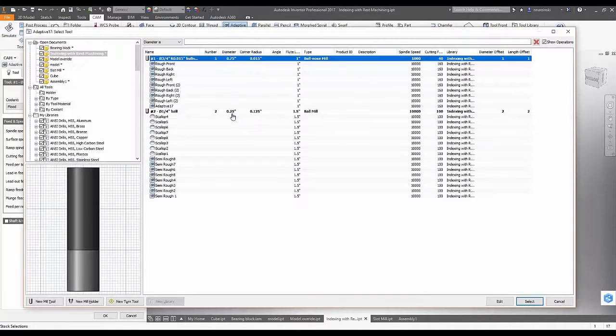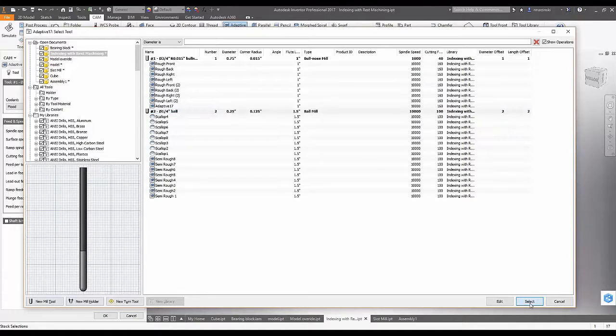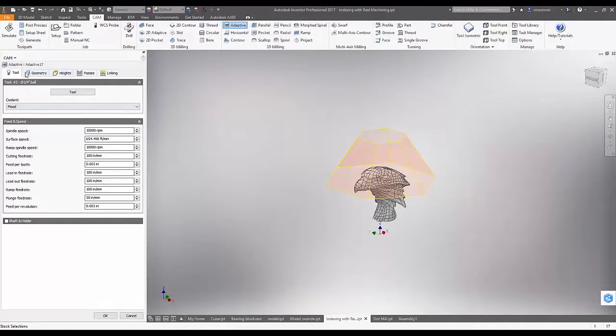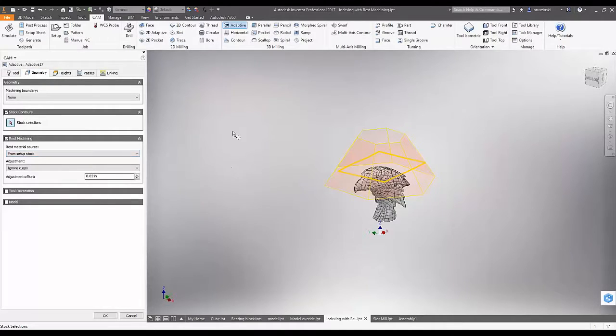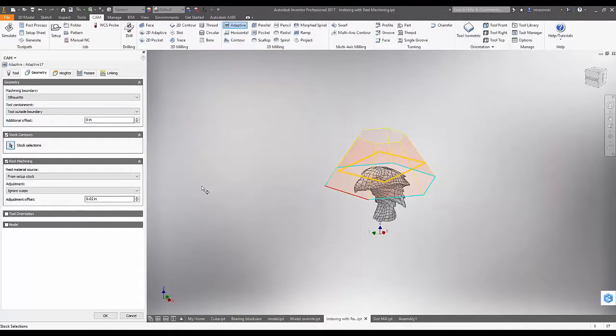This time we'll use a 1/4-inch ball. So this will be like a semi-rough type of operation. We've already got a good roughing operation in. Now I'm going to just knock off basically the edges of that. So I'll keep this to silhouette so it stays within the model.